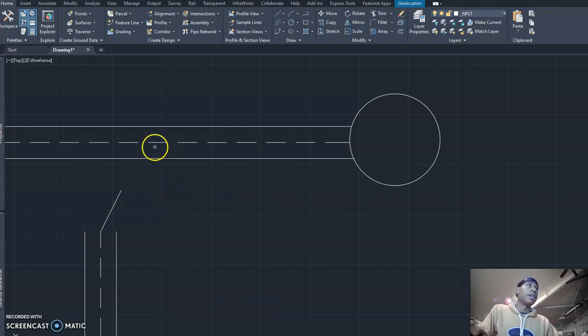So I guess that's an advantage of the extend command, is it holds the lines in place as well. So if you want to intersect something at a certain angle, you can do that. So as you can see here, it didn't change and get funky. It kept that same angular path towards the line that I wanted to intersect.